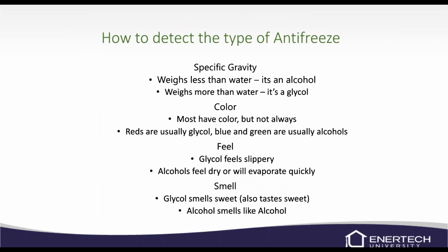How to detect the type of antifreeze that's in the system? A lot of times it's really hard, and you don't want to mix different types of antifreeze, especially when you mix an alcohol and a glycol. They don't mix very well. The specific gravity of alcohol weighs less than water, and glycol weighs more.